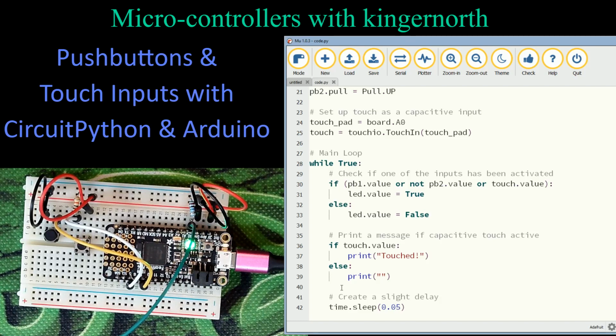It allows us to use a push button without anything on it. We can use a push button with an external resistor connected to it so that we can do an external pull up, which is the preferred way of doing most signals. We can do an internal pull up on any of these boards, and we can also do capacitive touch. Capacitive touch, like I said, has some limitations on the ground plane. That common plane is what's so important when you get into capacitive touch. Okay, other than that, I think that's going to wrap it up for this time.